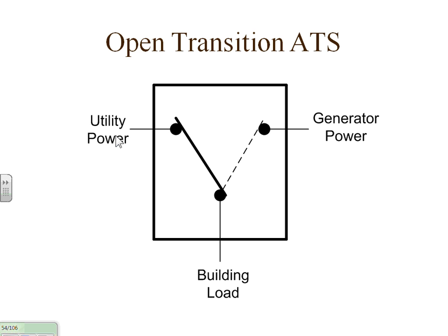And it's directly proportional. The heat of the engine exhaust is directly proportional to the amount of load that's on that engine. So the fourth time delay, we transfer back to the utility. We're going to allow that generator set to run for maybe 10, 15 minutes unloaded. Why? Now we're running cooler exhaust air through the exhaust pipe to help cool the turbocharger down a little bit before it shuts down. All four time delays.